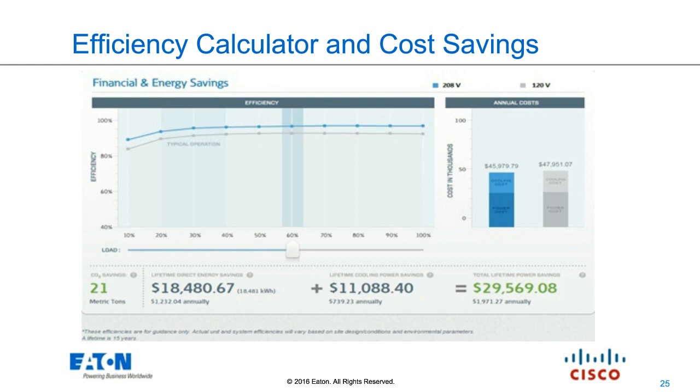So just to keep the math simple, I chose 1,000 watts, so that would be 1 kilowatt over the number of hours per year times, I think I chose 11 cents per kilowatt hour, and about 2% would be times 0.02. It comes out to about $20 per server per year.